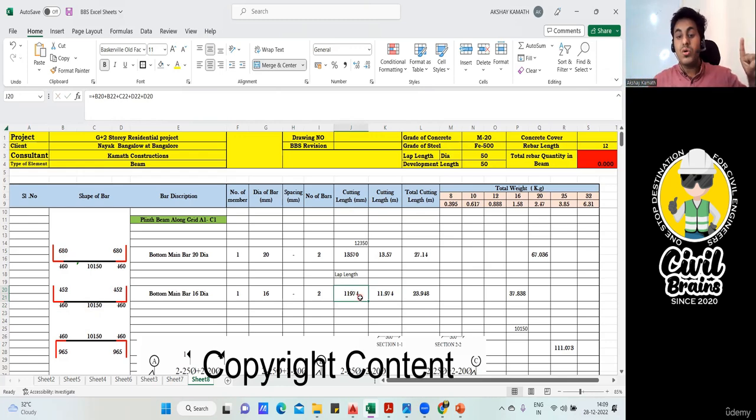And of course, around 26 mm will be left out. So that complete 12 meter bar is sufficient to make a shape like this. I don't have to do any lap length, so I did not add any. Whereas here it was coming to 12,430, so 430 mm was extra and we wanted to add a lap length. So I added one lap length there, but here it's not required.